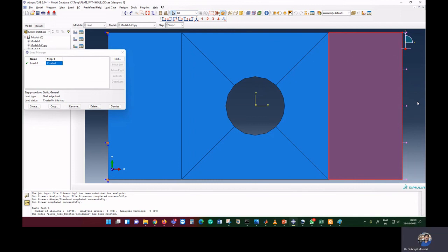So what you can do is fix the other degrees of freedom. You free only the x direction, or loading direction, and you constrain the other degrees of freedom so that you can avoid the error caused by the free node or free degrees of freedom here.